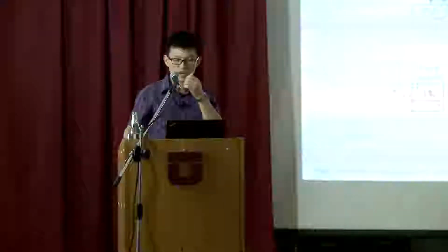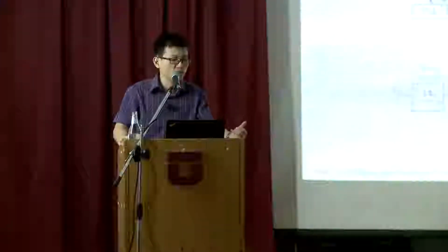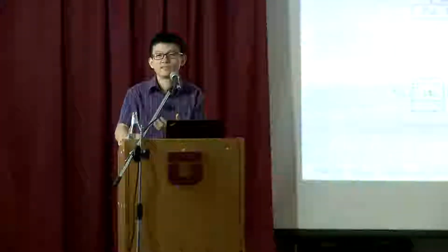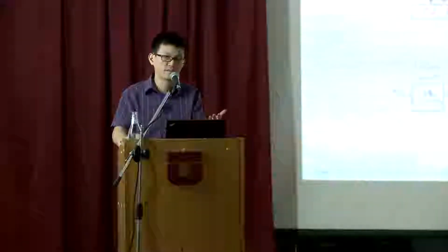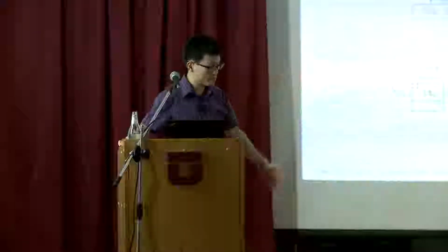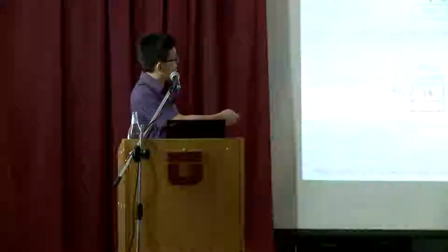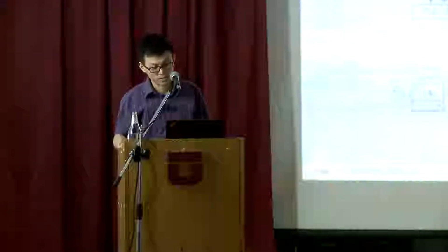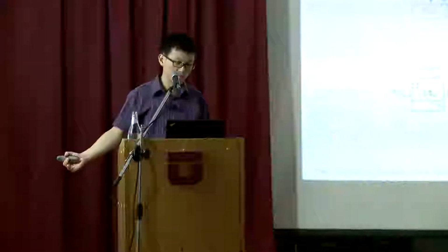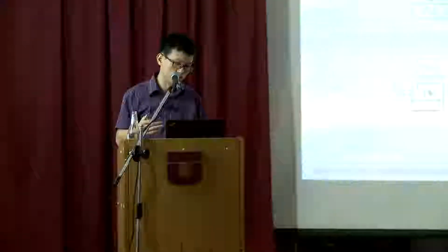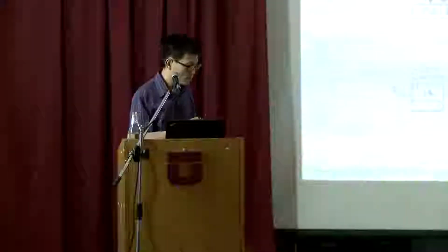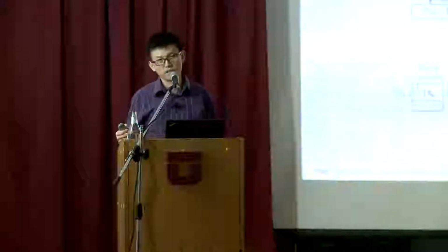So what do you want to do? Having this system, the first question you would ask yourself is: what kind of impact does this droop gain have on your standalone system? For example, the droop gain's impact on the stability or dynamics of your system, which can be either an electrical drive, an electrical generation system, or a DC-DC converter. That's the question you first have to ask yourself.